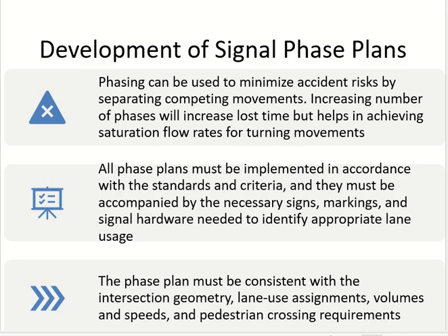The second thing is, one very extreme version of the phasing plan can be if I have 8 movements or 12 movements or whatever number of movements, I'll put one phase for every movement. So every movement is different. It has its own green time and yellow time. But with each phase, we have lost time. I told you there are 2 lost times, right?